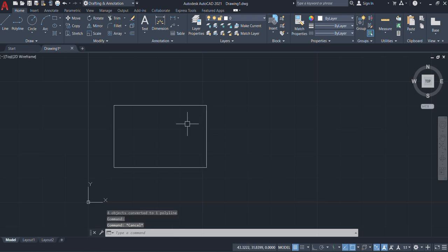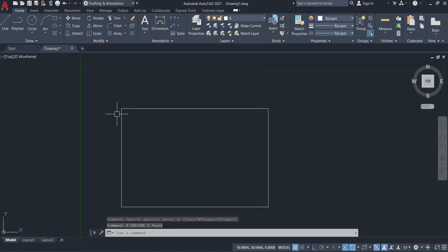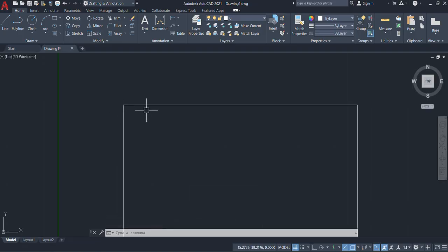Next, we have fillet and chamfer. We already discussed them in our mechanical drawing while drawing, but here I am going to explain fillet and chamfer once again. For fillet, F is the shortcut. Next, I want to specify the radius, because in fillet we get a curved shape like an arc, so we have to specify the radius. I am choosing radius in the command bar.